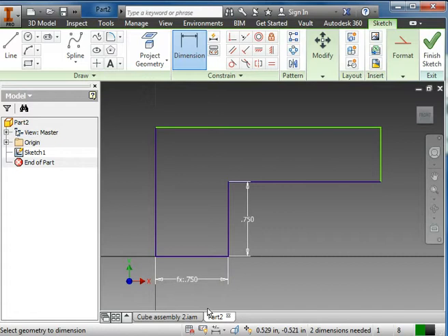The benefit of parametric dimensioning is that if you make something like our cubes, which are all 0.75, and you want to enlarge that in one step, you would find your root cube and change the number on the root cube and make it bigger. The whole puzzle, every piece of the dimensioning, would be bigger. Okay, we've got this done, and now we can go quickly.